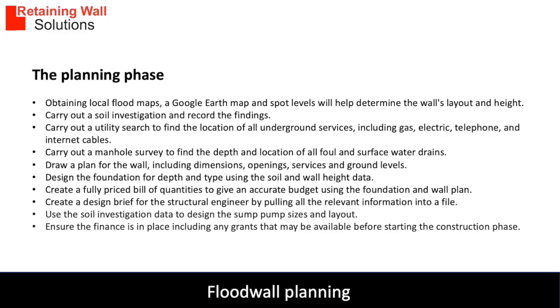Carry out a soil investigation and record the findings to determine the ground pressure. Carry out a utility search to find the location of all underground services, including gas, electric, telephone and internet cables. Carry out a manhole survey to find out the depth and location of all foul and surface water drains.